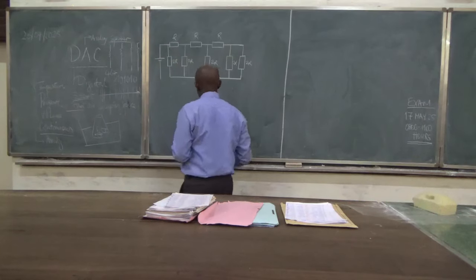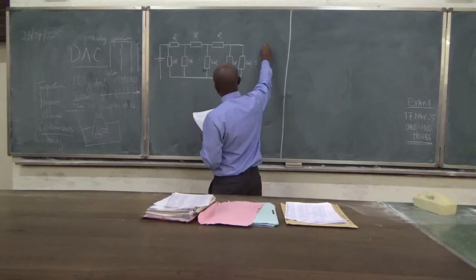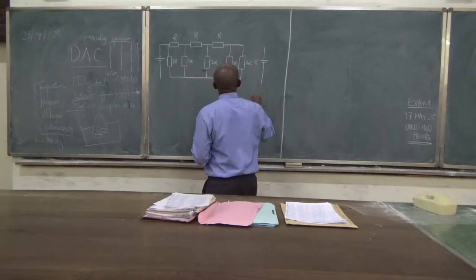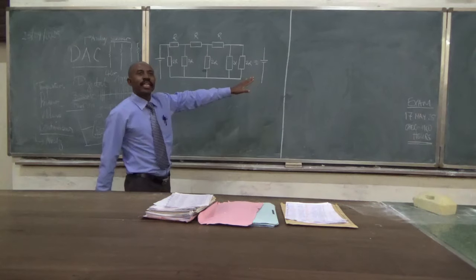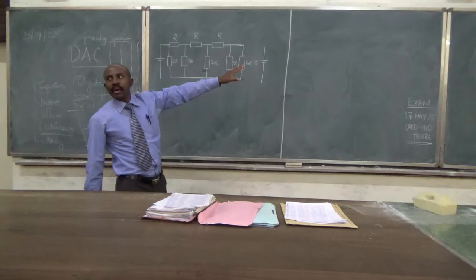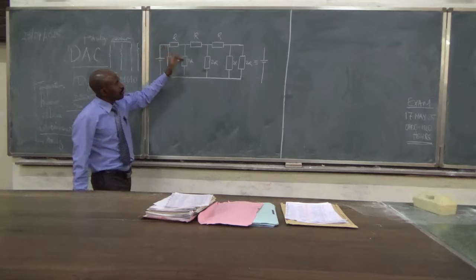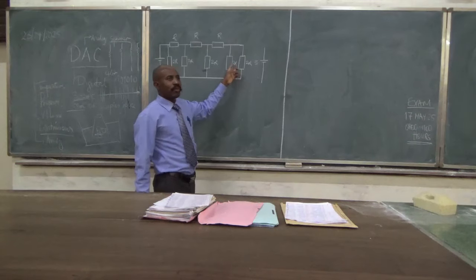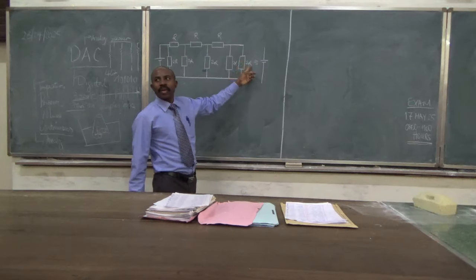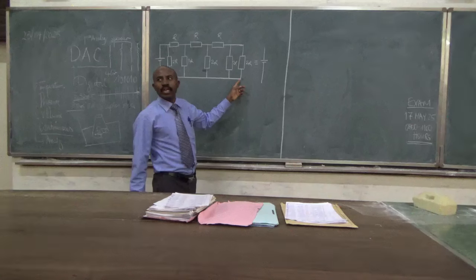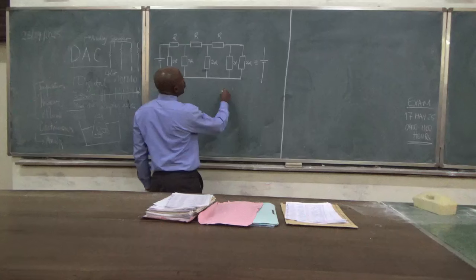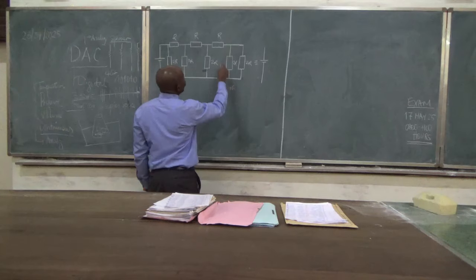And then this is equivalent to simply having the VREF here. And what is the effective resistance of this whole thing? We start from here. This is 4R squared, product over sum, 4R squared over 2R, which is 4R. Then we add it here.